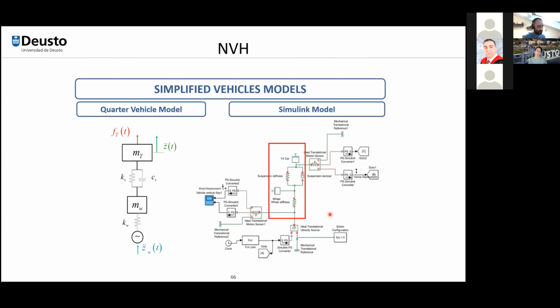Usually, the sources of vibration come from dynamic or rotating components, such as the engine or the motors. So we usually refer to low, medium or high frequency of vibration based on the RPM of such components. This is the first thing. The second thing is regarding the direction of the vibration. We usually refer to it as vertical or lateral vibration, based on the axis that the vibration is on.